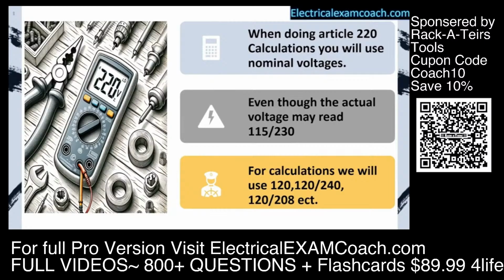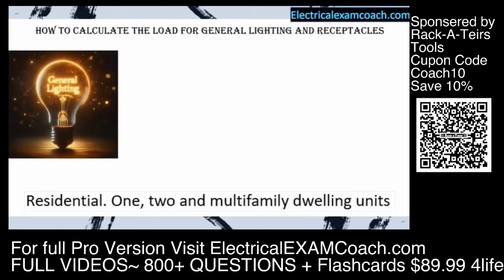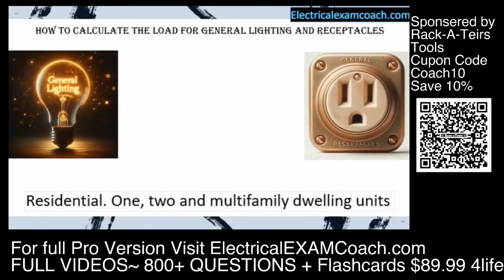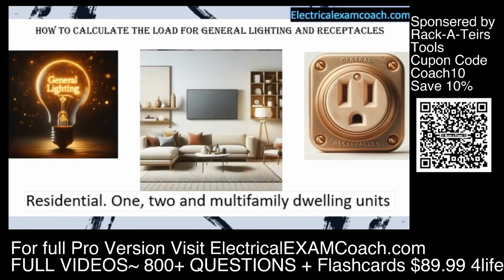readings might be. The first thing that we're going to learn about for our whole home load calculation is how to calculate the general lighting and receptacle loads. This is going to cover all of our general lighting and general receptacles in places like bedrooms, living rooms, hallways, everywhere that's considered a general area. We've grouped all of them together and come up with a very easy way to do it. Now, what I'm getting ready to teach you only applies to residential one-, two-, and multifamily dwelling units.